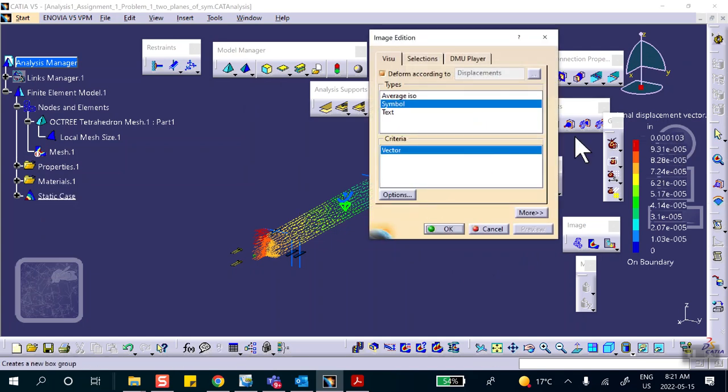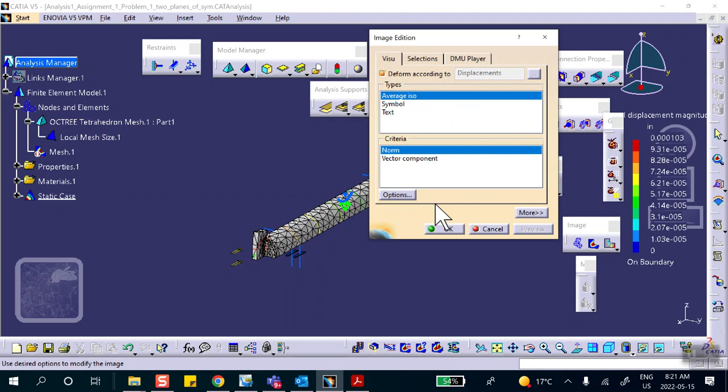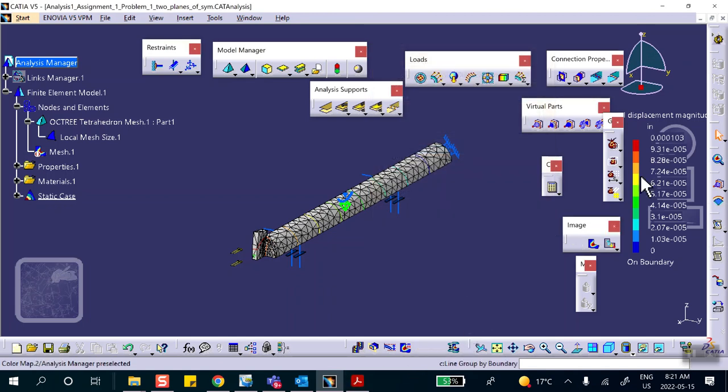You can see that that's nothing. This is a displacement, very tiny, and you can see why, because it's a gigantic, thick piece of steel. You're applying 400 psi on it. 400 psi is not much load. That's why there's very little displacement. There will be very little stress on it also.